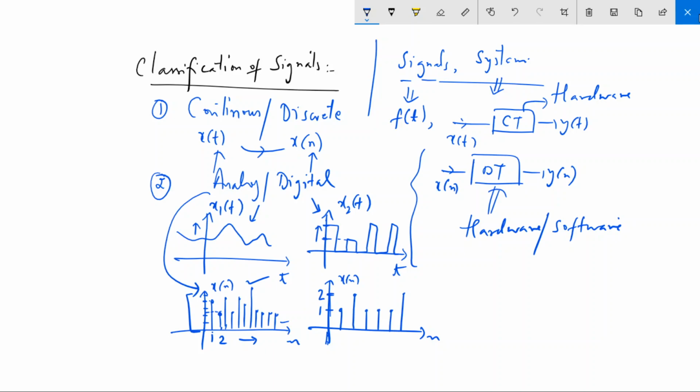So finally you get a signal, the quantized signal, in which time is discretized as well as amplitude is discretized. Now all these samples will have their amplitude values from a set of predefined levels. Okay, and then we finally convert this quantized signal into a binary signal using a coder.